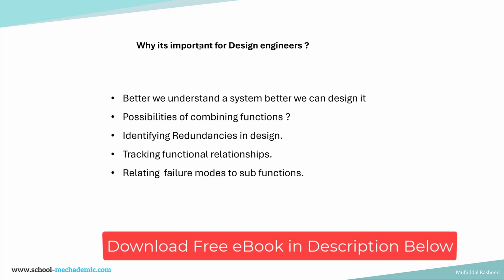Tracking functional relationships is also very important. If you want to track functional relationships between various sub-functions, this functional decomposition diagram will be very helpful. And when it comes to DFMEA, that is design failure mode and effects analysis, which has functional analysis as a very integral part of it, we can relate failure modes to sub functions by using this functional decomposition. So if you're making a functional decomposition diagram of a system, and you have the DFMEA, and you have a failure mode, then we can relate that failure mode to the various sub functions which are being affected.